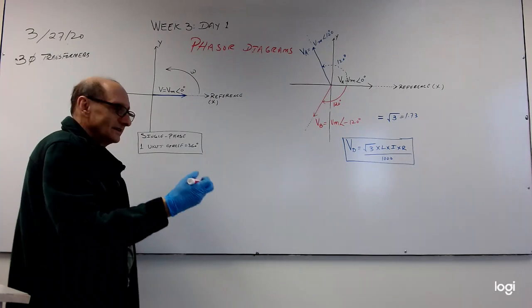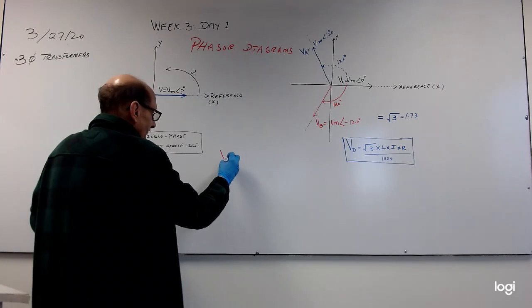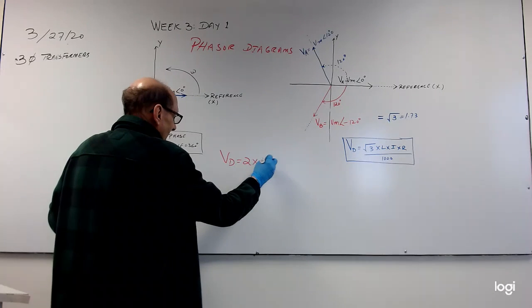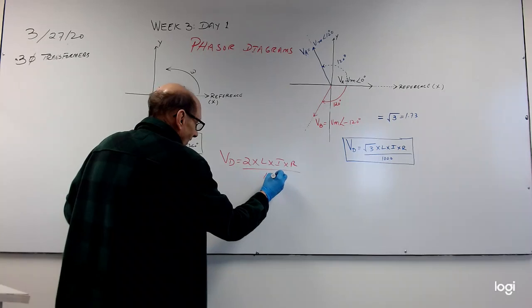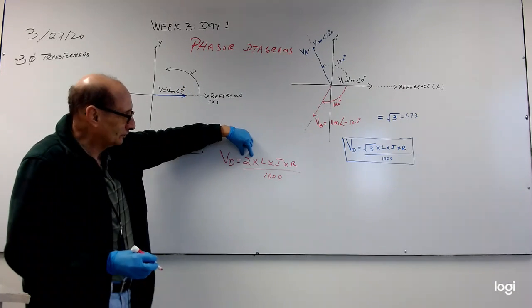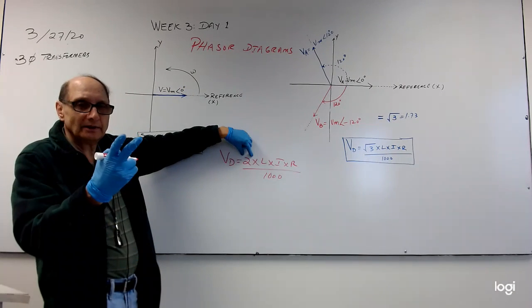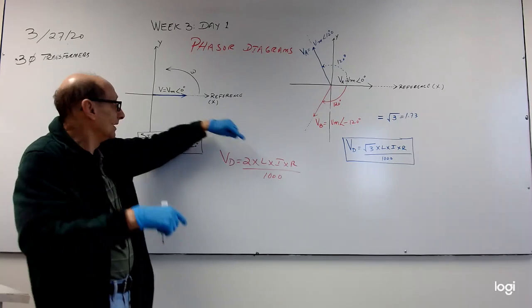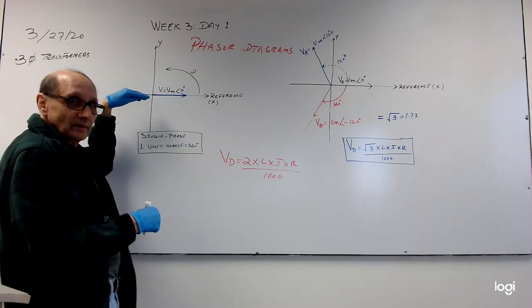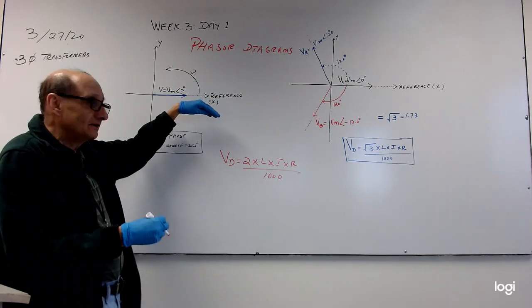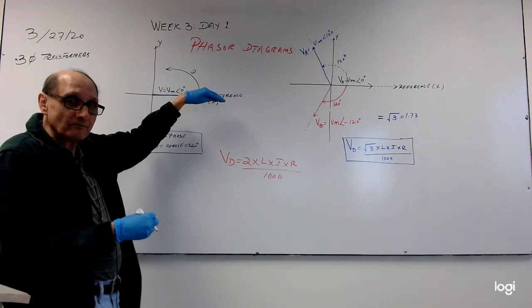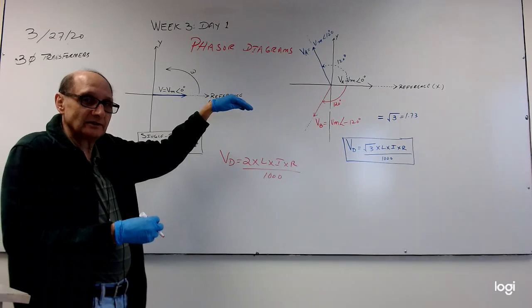One example, if you go back to voltage drops, that's equal to 2 times L times I times R over 1000. So in this case, this 2 is actually 2 conductors, round trip. So this is your hot wire, whether it's phase A or B, doesn't matter. That stays on the reference line on x-axis.